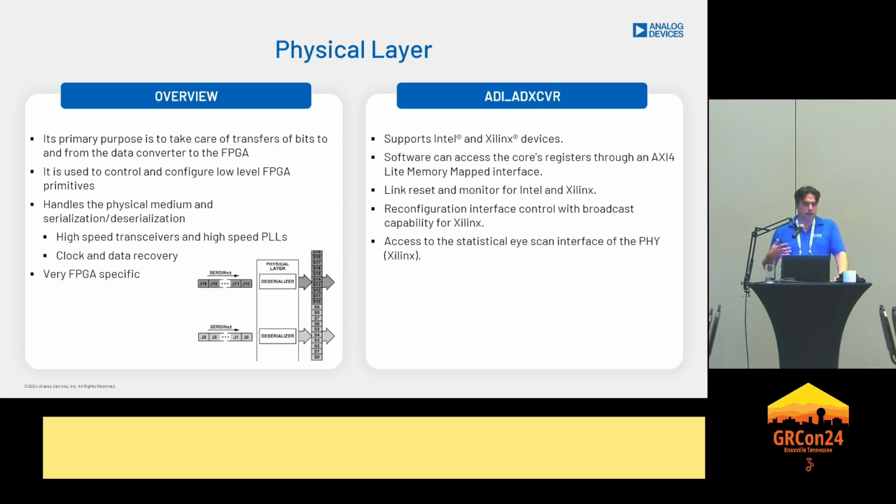We also added statistical eye scan capabilities. So for example, the Xilinx transceivers have that. That can always run in the back. You just kick it off. You can always have your physical running without interruptions, and you can periodically capture a bitmap that shows an eye diagram.